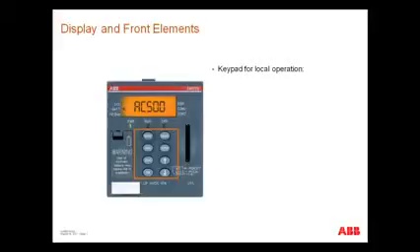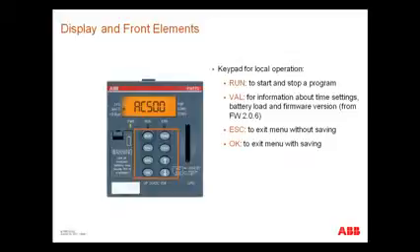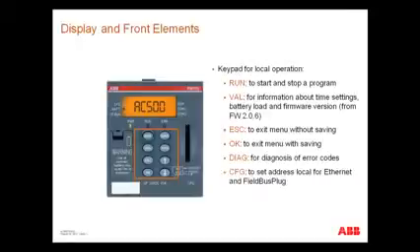You can use the keypad for local operation. With key run you can start and stop the program execution. With key val you get system information. The escape key allows you to exit any menu without saving. With key OK you exit any menu with saving. Use key diagnosis for troubleshooting. With key CFG you can locally set addresses.